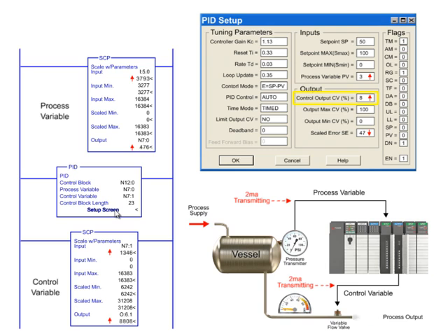By increasing the control output, the error is reduced to attain the set point as the PSI is raised in the system. In other words, the valve position is gradually closed to reduce the pressure loss. Upon reaching the set point in the system, the control output and scaled error is reduced to 0.